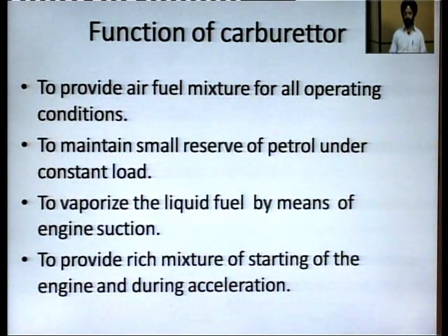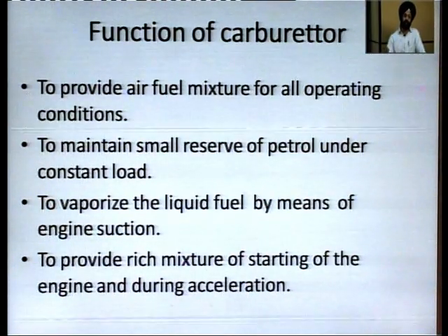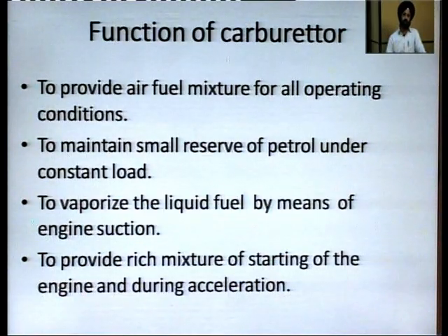Now we have learnt what carburation is, what a carburetor is, what it does and how it does that. During normal running, when the throttle is open at constant speed, the air will flow through the venturi and the fuel supplied from the main jet will mix with it, get atomized, and be supplied to the engine.